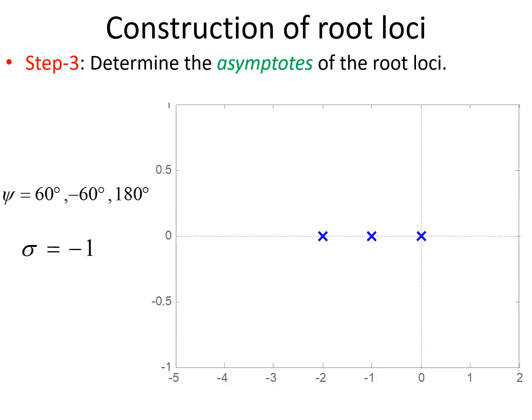Now you have to plot this centroid by taking sigma as equal to minus 1. If you can see here, sigma is marked at minus 1, and we are first drawing the first asymptote, which is shown in red color with 60 degrees or minus 60 degrees. You can in turn take it as 300 degrees also, one and the same, and 180 degrees.